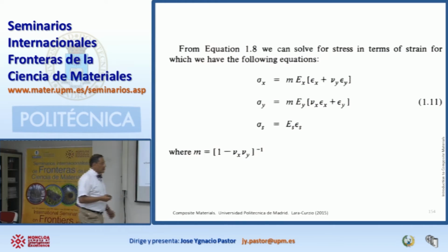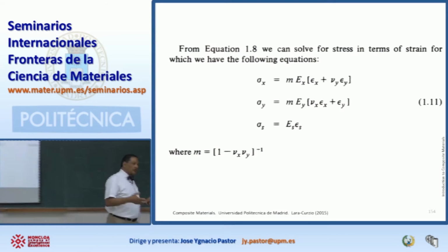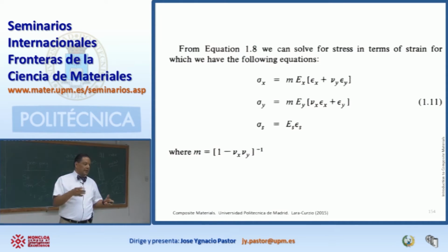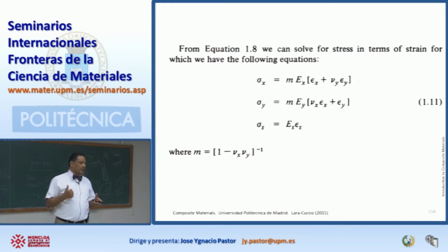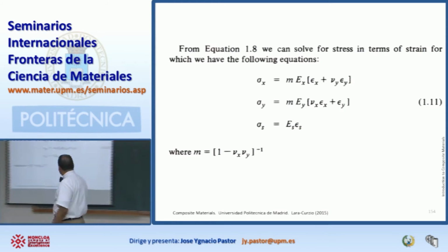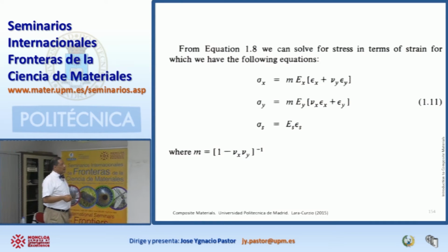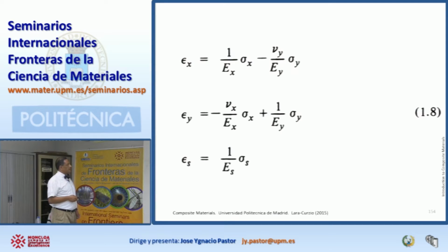Now, in the case of the fuselage, you may want to calculate your strains because you know the pressure inside the fuselage. You pressurize the fuselage. You know the pressure in megapascals. You can calculate the strains. There may be some applications where you are actually applying a strain, and you want to know what the stress is going to be. And these relationships are going to give you values of a stress as a function of a strain. But once you know your elastic constants, you're all set. They will give you one if you know the other.